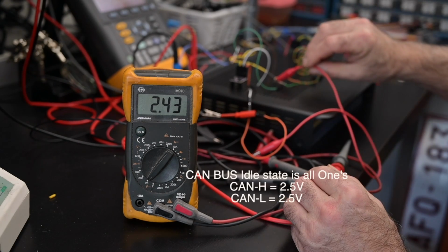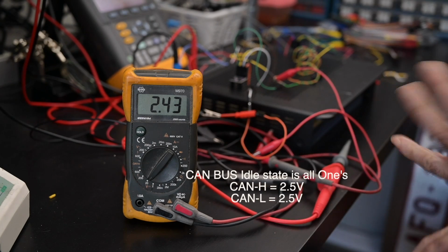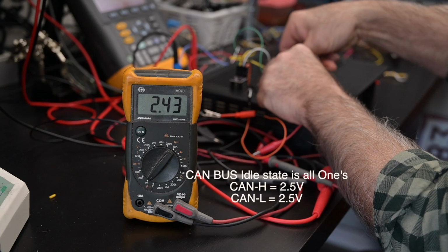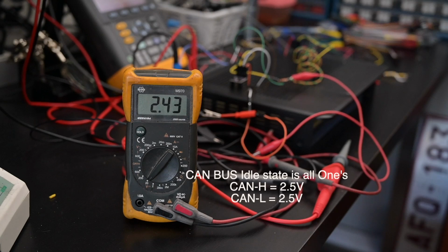Right now, I'm looking at the CAN high, and I'm applying a steady 1 signal towards the transceiver, and you can see the bus toggles to 2.4 volts. If I move my probe to the CAN low, it should be about the same. And as you can see, it's 2.4, so there's almost no difference.